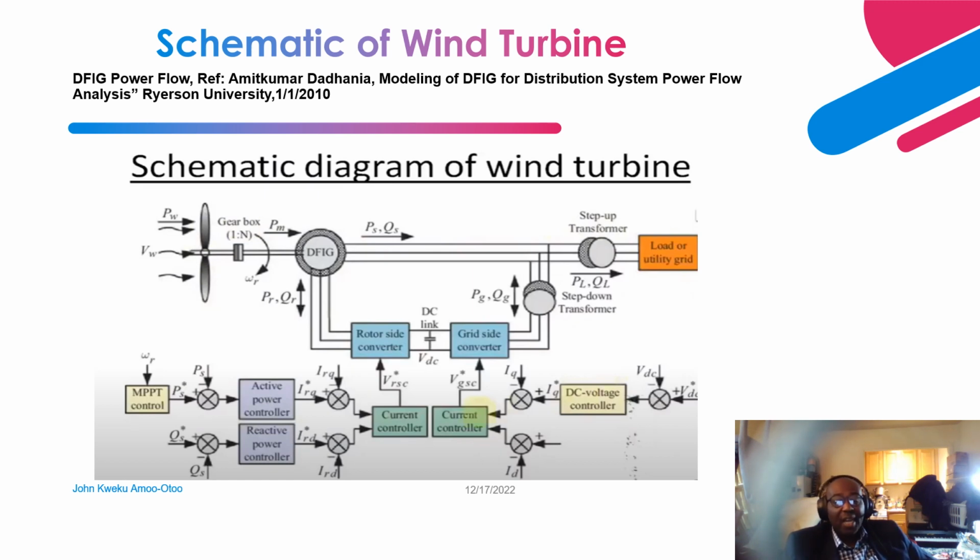On the other side, the grid side converter, on the other hand, we have a DC voltage controller. You have a set point of the DC link voltage that it is supposed to control, right? Then there is the measured DC voltage. These are based on measurement devices in the controller that send the signal to this PI controller.